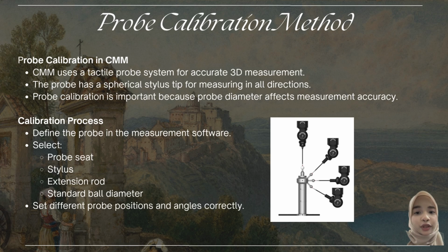So during calibration, the probe touches several points on a standard sapphire ball, normally from 7 to 11 distributed points, which are measured to obtain accurate data. And then the software analyzes the collected X, Y, and Z coordinates to calculate the ball center, diameter, and shape error. A small standard deviation indicates better repeatability for enhanced, higher accuracy.